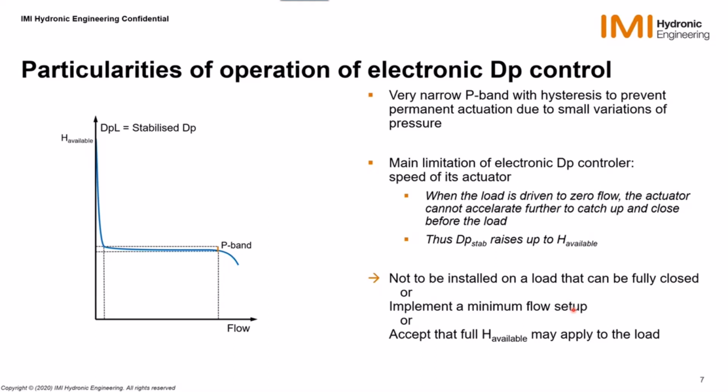Now, this being said, the application where we have seen this going, as I mentioned earlier in France with the Belimo EDPV, are zones of a building, typically a floor, with quite a few terminal units, and where basically the assumption that is taken is that there is never all the terminal units closed at the same time, or it is not happening in normal circumstances.